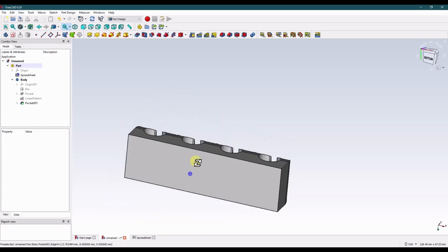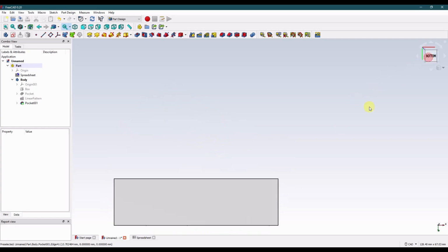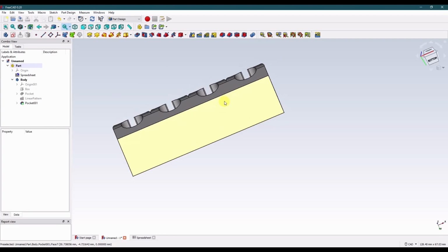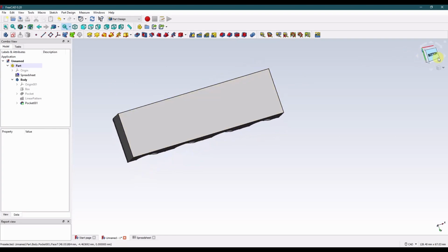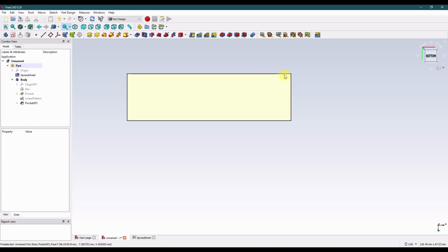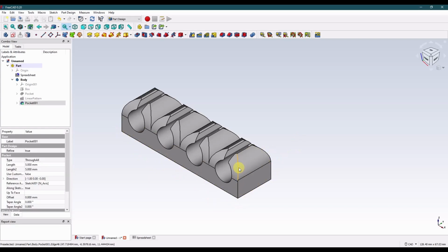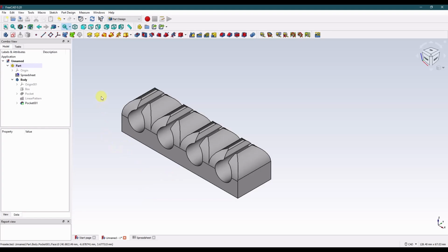Another thing you could do, and I don't recommend this, but if you really wanted to have those rounded edges, is to create a cut feature, kind of like we're doing with these other pockets for the chamfer or the fillet there, and you drive the length between the cuts inside the sketch with the spreadsheet. So no matter what length you're choosing, it's always going to place those cuts here. And that's fine for the corners, but then how do you take care of these? And you can do it sort of.